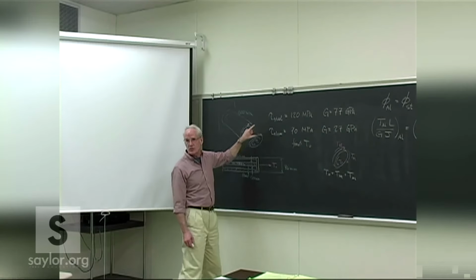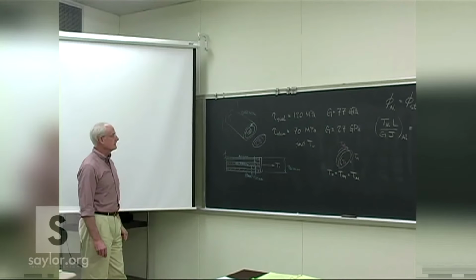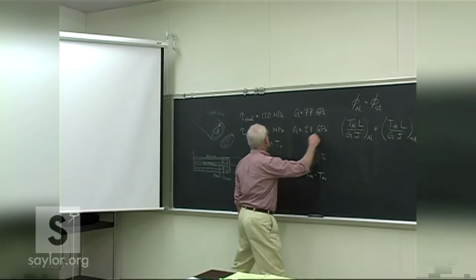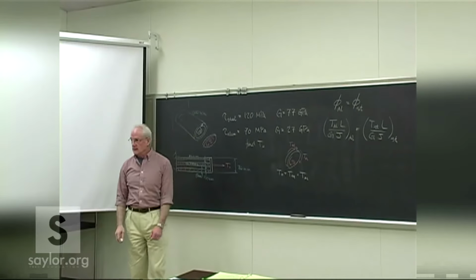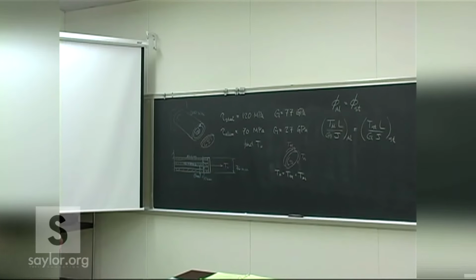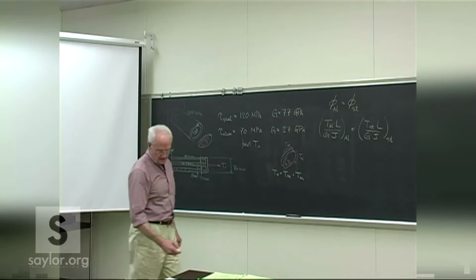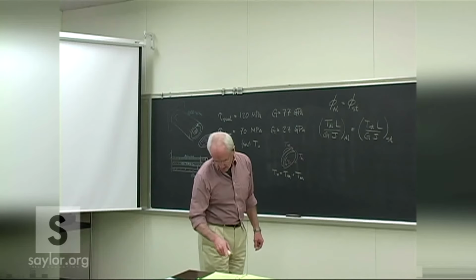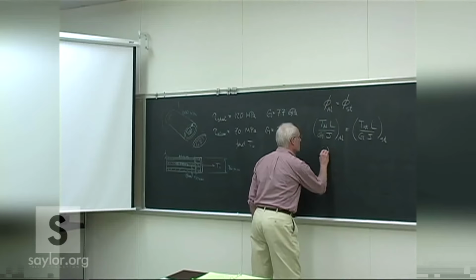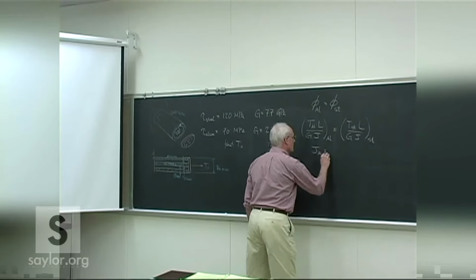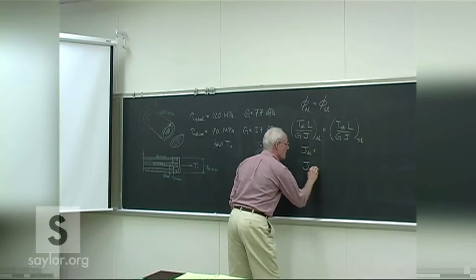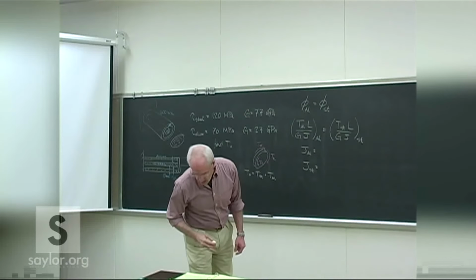So we have to assume one of them is at the limit and then use that to calculate what the total load is, then check that for the other one, and if it's over the limit, then we know our assumption was wrong and we have to redo it the other way. So we can add that by bringing in the stress limits. Just for a little bit of help here, I'll give you the two polar moments, so you don't have to bother with calculating those.